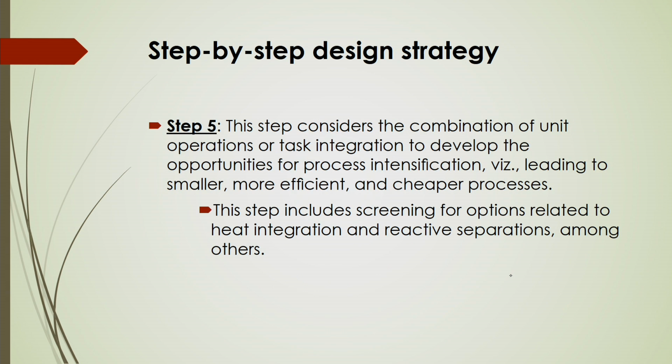And the next step is the combination of unit operations or task integration to develop the opportunities for process integration, leading to smaller, more efficient and cheaper processes. So, this step includes screening for the options related to heat integration, or you can say reactive separations, or others like extractive distillation or absorptive distillation, all those things to be considered there as an integrated system.